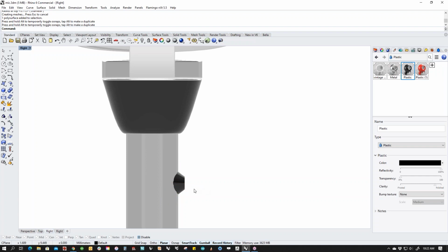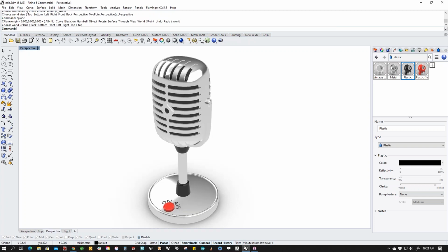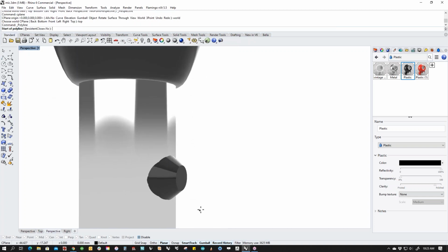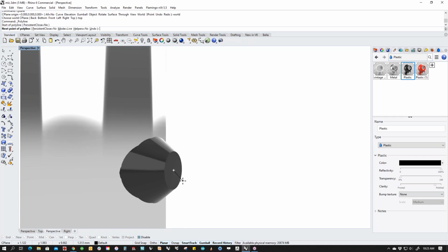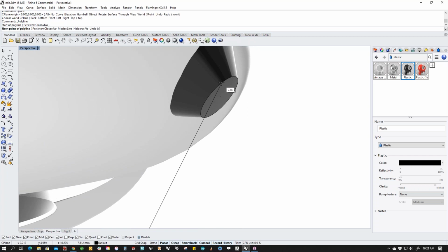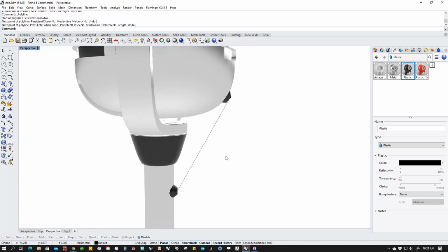And then I'm going to just steal that, stick it up here like that. And then I'm going to draw a curve from the center of this guy. And I'm just going to use a straight line because it's easiest to nail down. And then we'll do some edits to it. So I can snap center to center so I know that the ends are going to touch correctly.